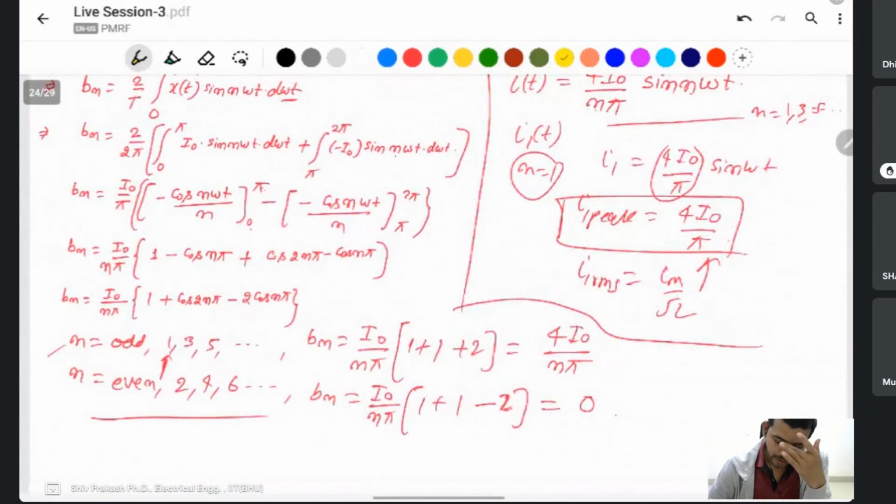But for practical purposes, how many harmonics? Infinity, that is the ideal case. But when we calculate it, up to which harmonic is sufficient to simulate the waveform? I think 7 to 8, because the magnitudes are very small, no?